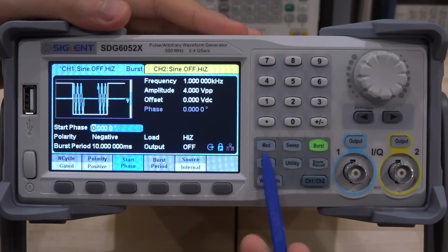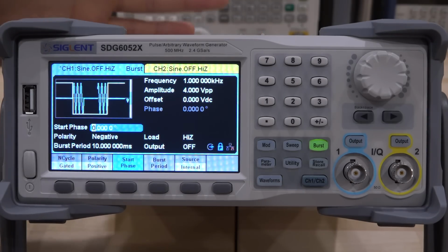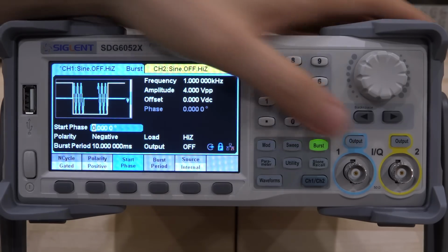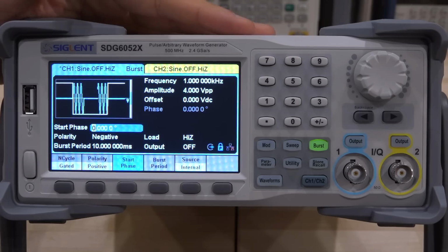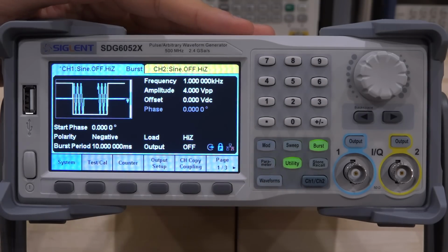So once you have the setting between those, now essentially your waveform is set, and then you can enable the output or disable the output. So it's really quite straightforward if you go at it in a layer at a time to get the waveform creation the way you want it. Now under utility, you can set up the counter, or you can do waveform copying. You can add waveforms, you can couple the channels to each other, and we will go and explore all of those things.